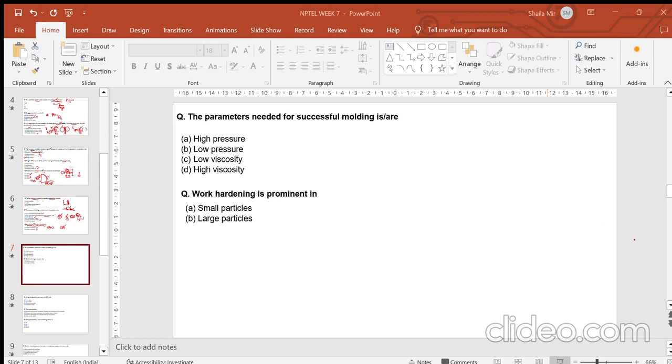So you will see that there is a slight difference in the densities. This is 8.75, this is 8.1. There will always be some difference in the density values if you calculate using this method or that method, but both methods are correct. You can calculate the densities based on your theoretical density when you have a mixture of powders, and there could be a mixture of three powders or some other powder.